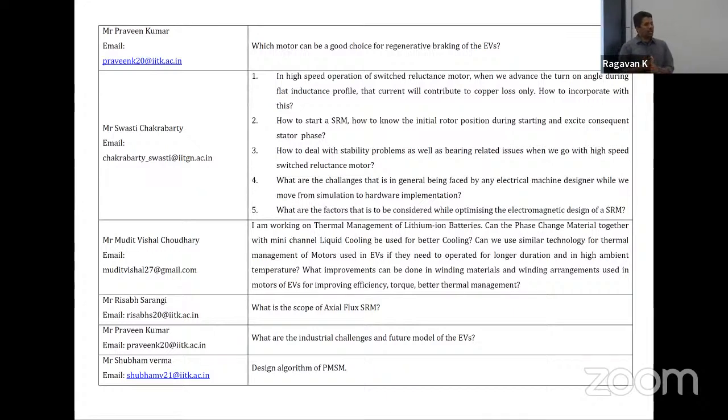But once again, if you go too far into it, you will generate a lot of heat. So that is a variable. So the first function is torque ripple, but the second one is heat. Heat can be a bigger killer than ripple. Acoustic noise you might be able to handle, but extracting heat can lead to a subsystem that has to be over-designed. So I would ask, is that something that you actually are facing in terms of heat?